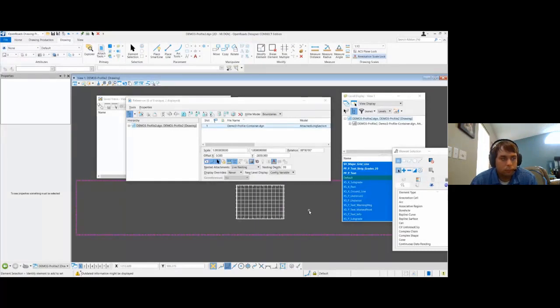You can also use that level display application or VBA that Bentley released that I showed back on the plan view slides with your profile view display. It has the same limitations or restrictions. Display override set to never is still going to override whatever that application is doing, as well as it's not integrated with ProjectWise, as well as it doesn't work if you have the do not override variable display turned on. So that is still available. Just note the restrictions on that.